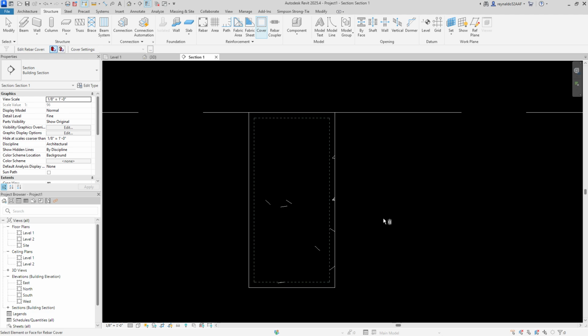If you want a universal setup where you want an offset on all 4 sides, then you would do the pick element, and then this one would offset everything equally. So we want to do the first one, and before we can change the offset, we want to pick the side we want to change, which is this one. We click it, and once you click it, it'll activate this part right here.